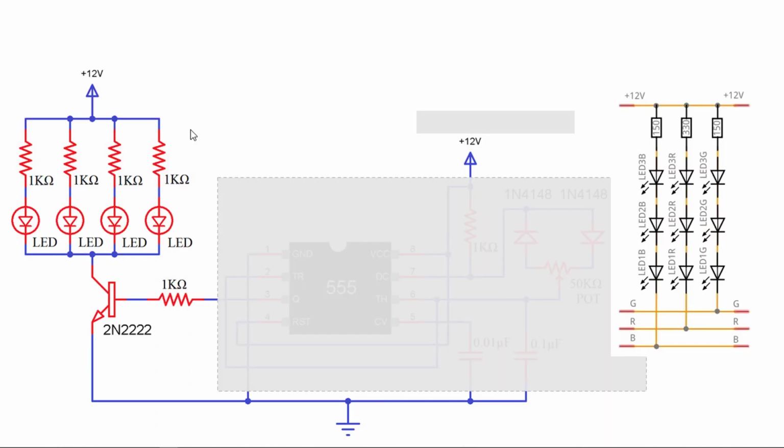So make sure that you match up your power supply with what you've actually got. Okay, now this is kind of looking at what the dimmer does. So there's actually 2 images here, and I kind of grayed out the circuitry because all that we care about is that the dimmer controls the current flowing through that transistor, 2N2222, and it controls the current flow through those LEDs in parallel.